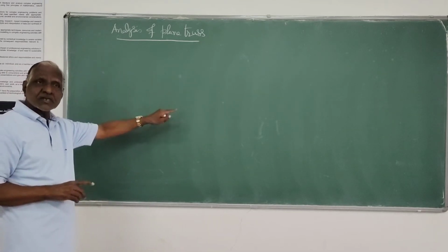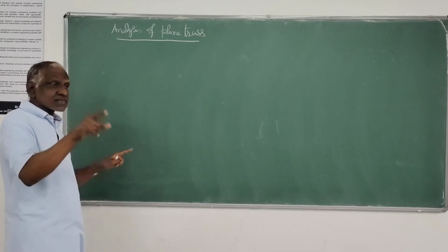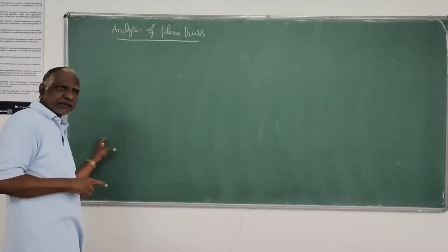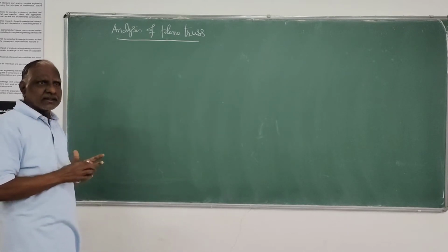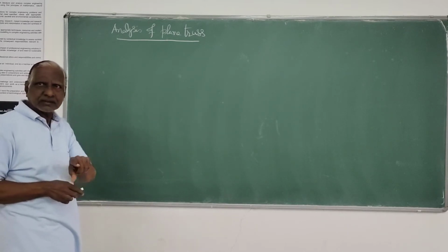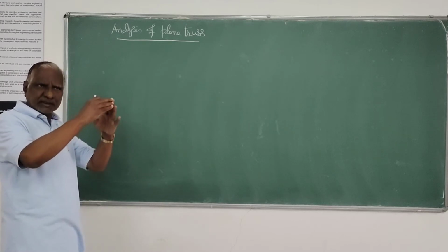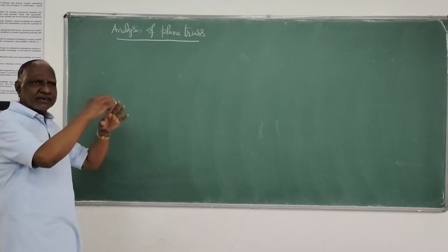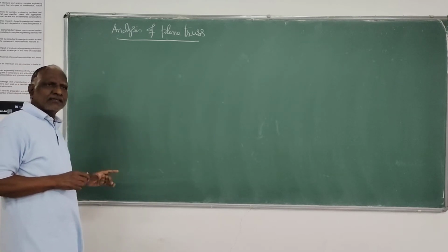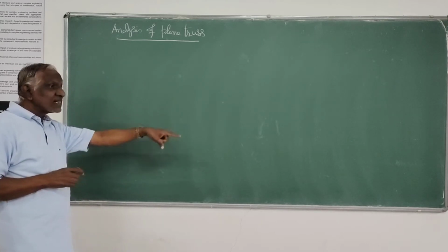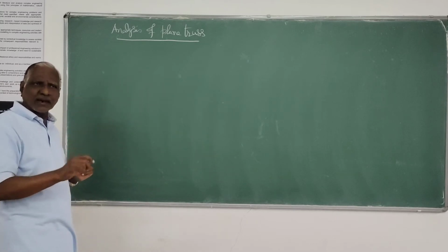Whereas here in a truss, you cannot expect that, because the truss is an arrangement of line elements in the form of triangles. The moment I say triangle, the arrangement of the elements should have inclined lines. So whenever members are inclined, we cannot adopt the system approach for hand computation.